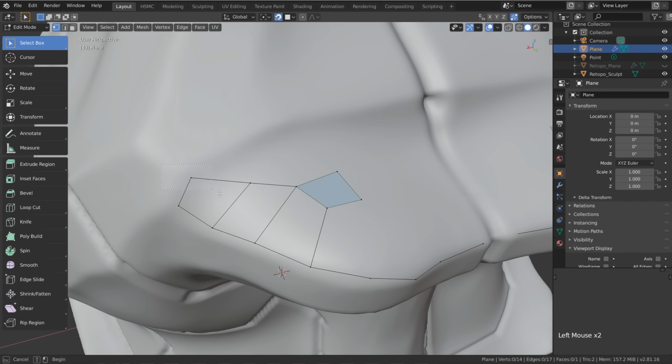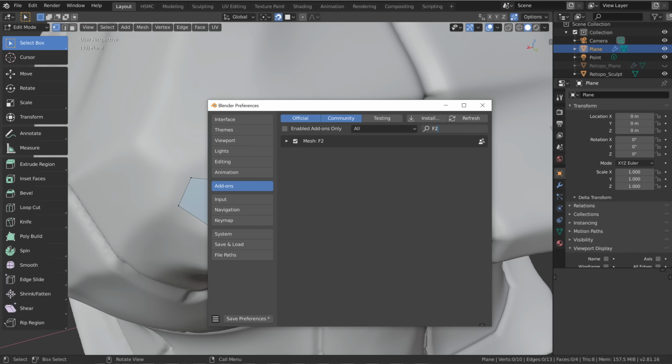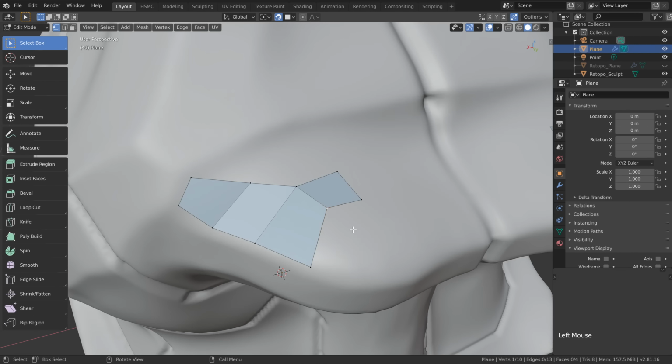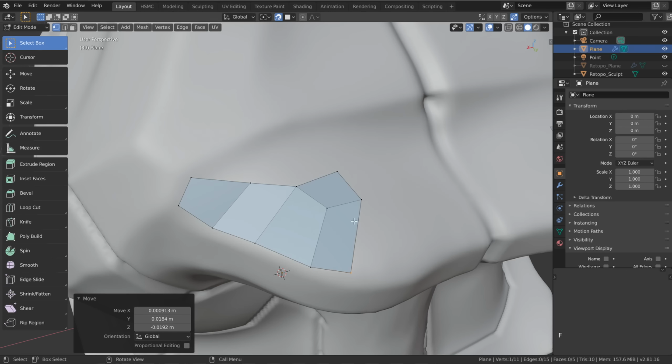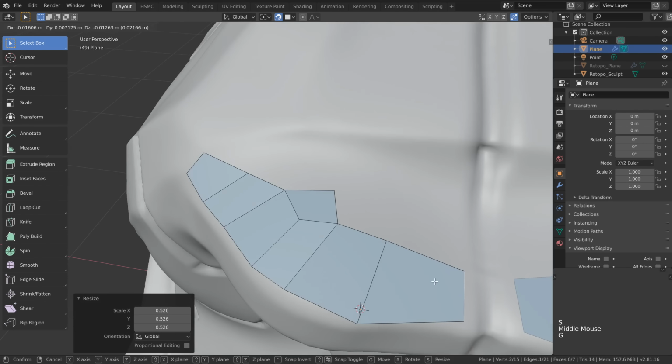And then once we have all the wireframe that we want, we can just press F and the individual faces should get filled in for us. But I'm going to delete those with X, as I think it's probably easier to go with the general creating of faces, especially if we find our F2 add-on. Making sure that that is enabled there helps things along. For example, we can select that one vertex and press F and a face gets created from that. And it's still possible to control click to extrude in edge select mode. So I've jumped over to edges and then control and right click, control right click, and then we can scale down or rotate these into position.